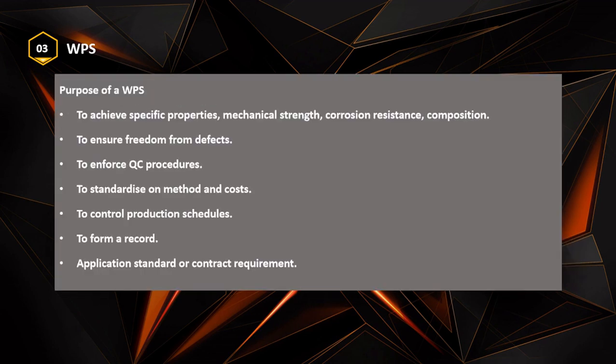The purpose of a WPS: to achieve specific properties, mechanical strength, corrosion resistance, composition. To ensure freedom from defects. To enforce QC procedures. To standardize on method and costs. To control production schedules. To form a record. Application standard or contract requirement.